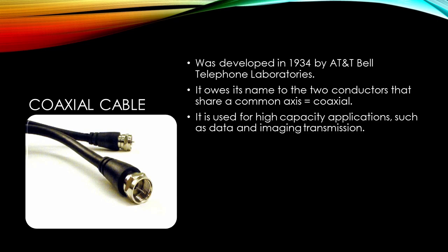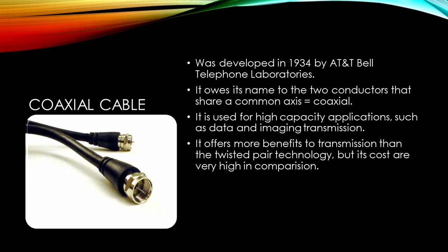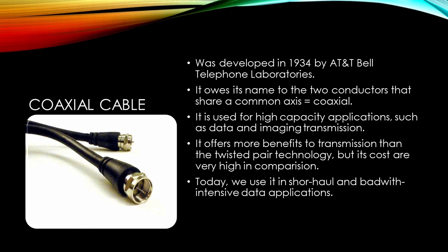Coaxial also offers different limitations in distance because the thicker center conductor offers less resistance to the signal, and transmission can be made over a significant distance. In terms of security, coax is a very secure technology since it's really difficult to place physical taps on a coax without detection. This transmission system is considered expensive in comparison to the one we saw before, and it is used in high-capacity data applications. However, its positive performance characteristics can outweigh that cost.